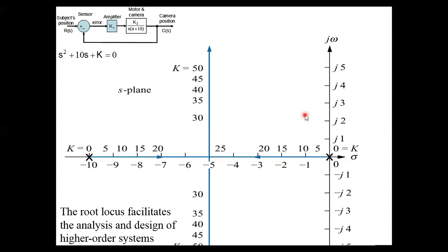So we can see that regardless of the value of gain, the real part of the complex poles is always the same, since the settling time is inversely proportional to the real part of the complex pole. For this second order system, the conclusion is that regardless of the value of gain, the settling time for the system remains the same under all conditions of underdamped responses.